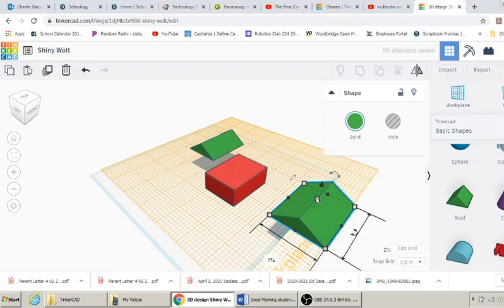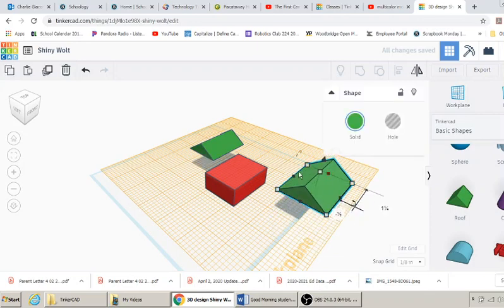And we need to increase the height by 1/8 inch. So our roof is going to be 1/8 inch thick. That's why I extended it 1/8 inch in each direction. So 1/2 inch plus 1/8 inch would be 5/8, 0.625. All right. And now we have to hollow it out. So that's why I didn't join together this segment.